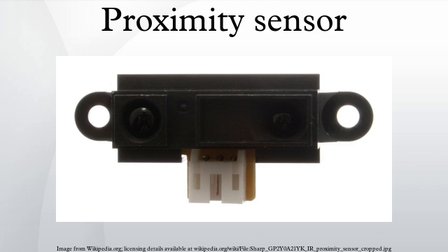Proximity sensors are commonly used on smartphones to detect accidental touch screen taps when held to the ear during a call. They are also used in machine vibration monitoring to measure the variation in distance between a shaft and its support bearing. This is common in large steam turbines, compressors, and motors that use sleeve-type bearings.